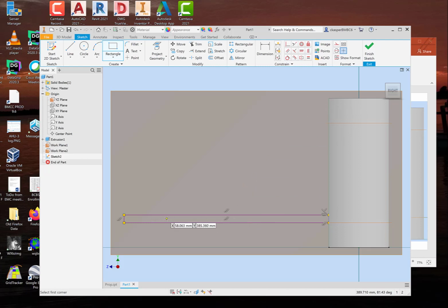You don't have to have the plane even under any part of your sketch, as long as your sketch is in that plane per se. Yeah, I know what that sounds like. But you can see that plane adjusted itself to cover or be underneath what you just drew.